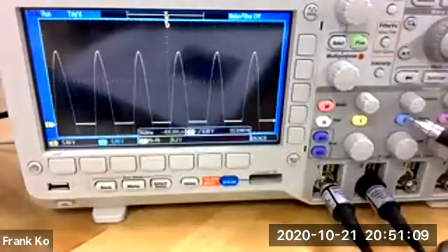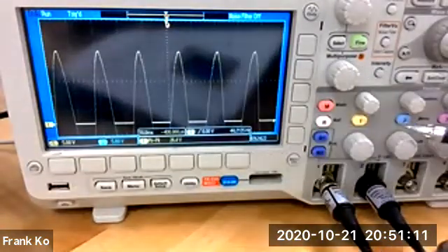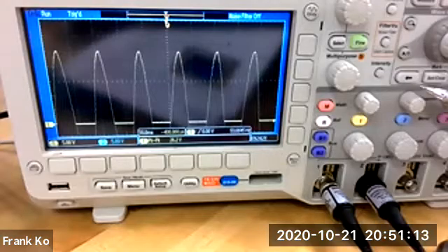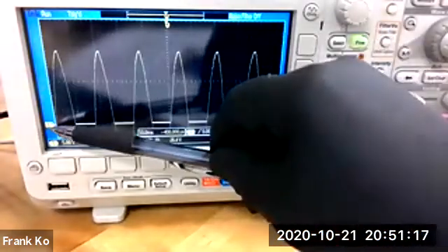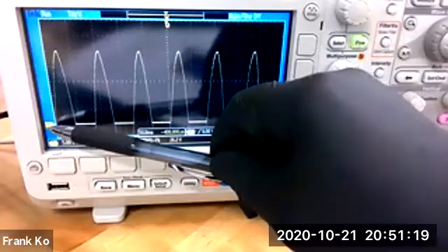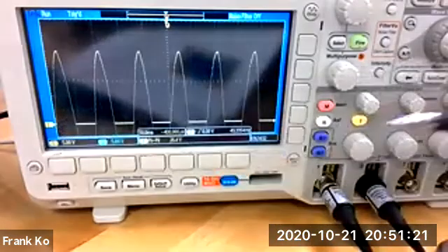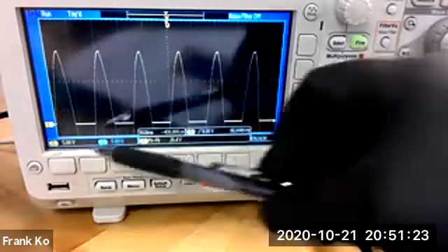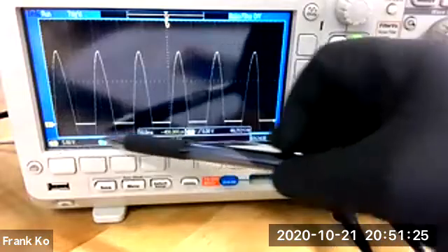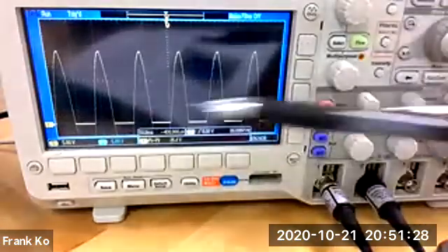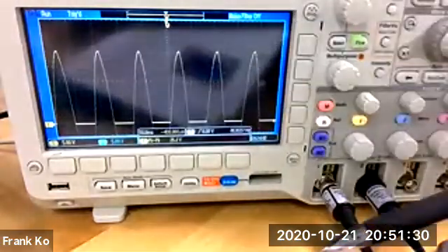And you want to do the same with your channel 2. Use the vertical position knob of channel 2, bring it down so that the blue and the yellow flags are on top of each other, and set them to the same scale, 5 volts per division, okay? So could you do that, please, and get your waveform set up this way?